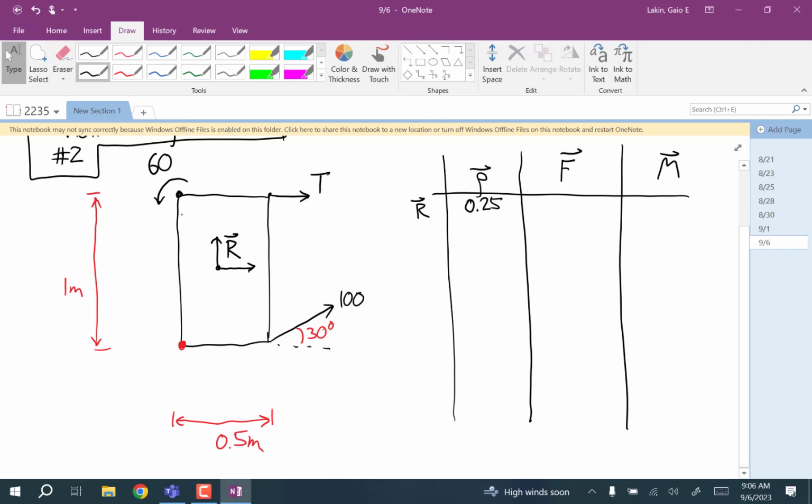You have to go in the positive y direction 0.5, to get from the about point to that p. Stop me if I do a step that you don't follow. The force vector is Rx, Ry. And so the moment is 0.25 Ry minus 0.5 Rx.